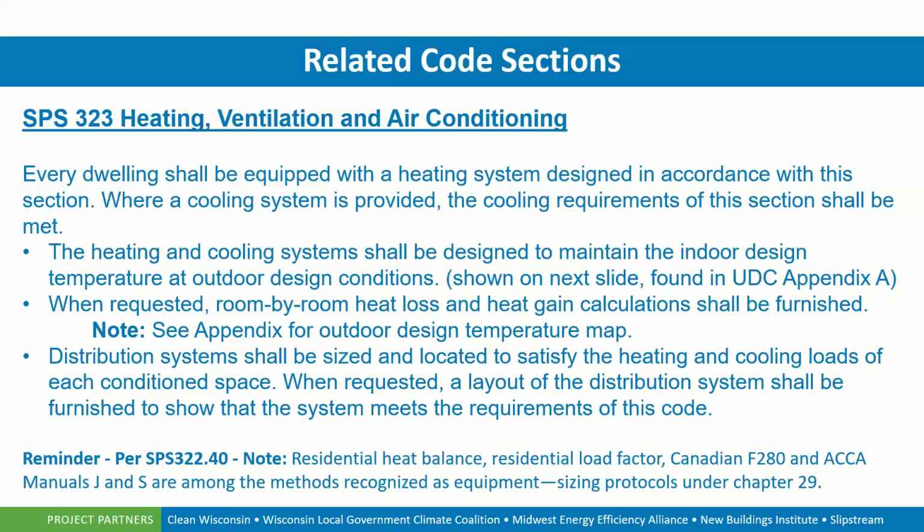Again, knowing that we can accomplish all of these passages with Manual J, S, and D. Making sure we have proper loads, heating and cooling load requirements, we have proper sizing of equipment, and we have proper distribution system layout and design.